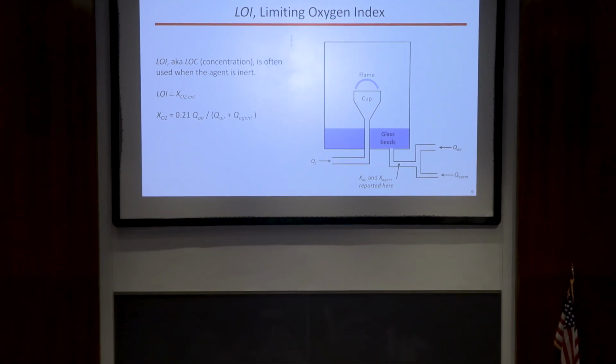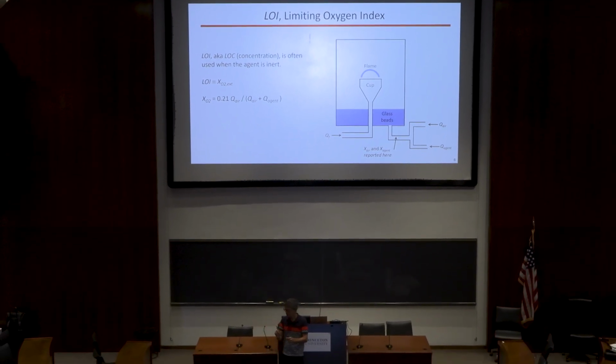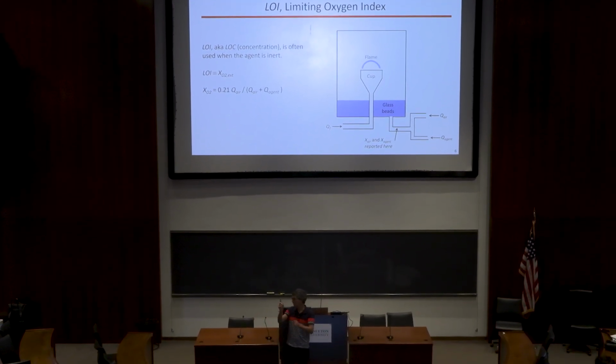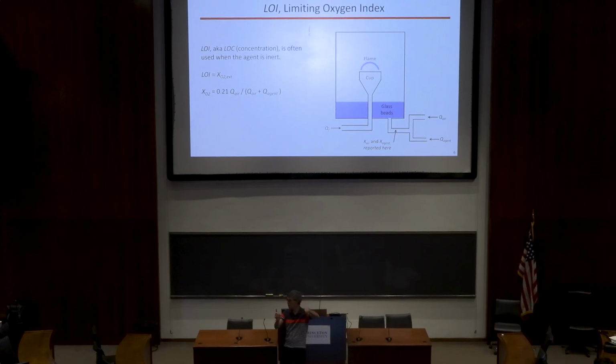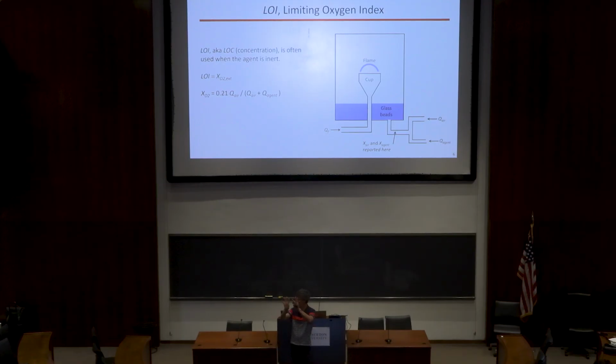And they also uniformly distribute the flow. So if you didn't have glass beads, you would just have kind of a jet of this air going up, and you could have recirculation and parabolic profiles. You really want a constant velocity, parallel flow going into your flame region.